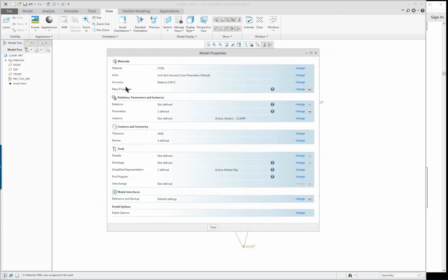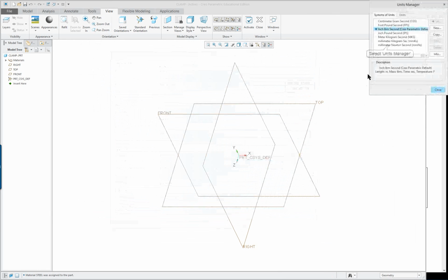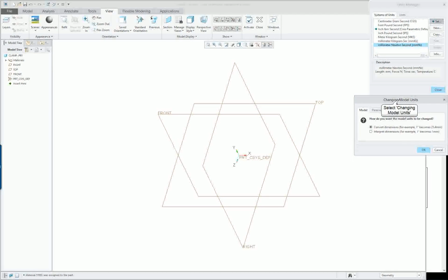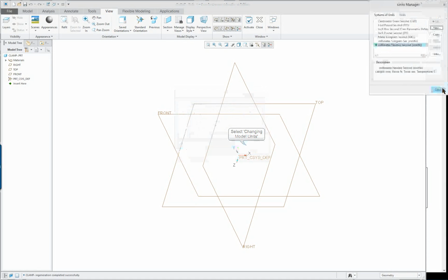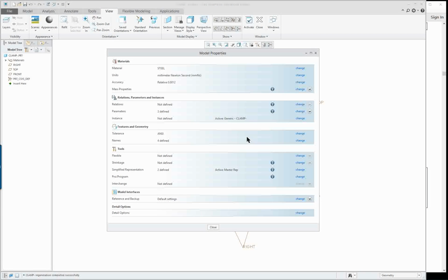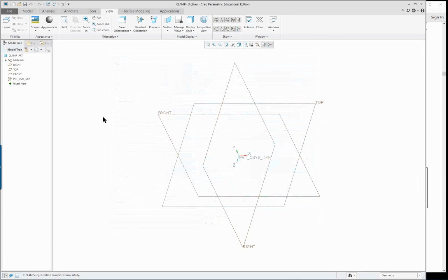And the next thing we want to do is set our units, and we're going to set them at millimeters, and we click set. And this sometimes confuses people. Very seldom you will ever use the first one. It's just best to always click the second one. You normally just make a mistake in not selecting the units, and it's really 1:1, 1 millimeter to 1 inch. So that's the conversion. You don't want to convert. You want to just use the same whole number. So, okay, close, and close.